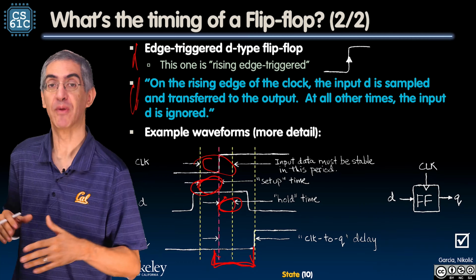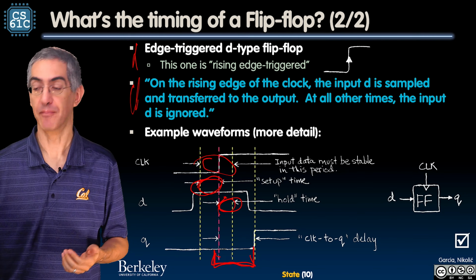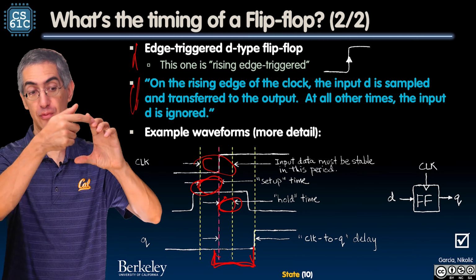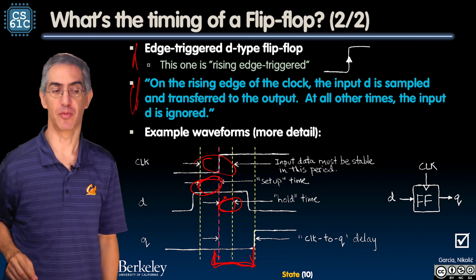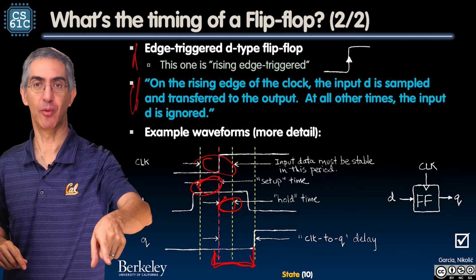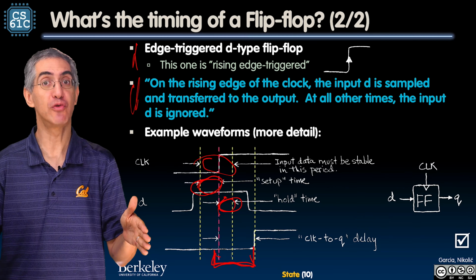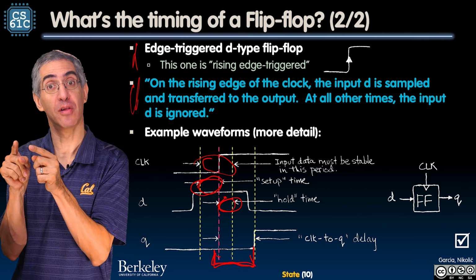Could happen before then, but when you go to Fry's Electronics to buy a flip-flop, you say, here's some numbers. There's 3 spec numbers. And usually they're really small numbers, picoseconds often. And I'm gonna say, well, how about this one? That's the bargain bin. What's in there? Well, that's with a really huge clock to Q delay. Oh, how about that expensive one? Yeah, that's a really small clock to Q delay, right?